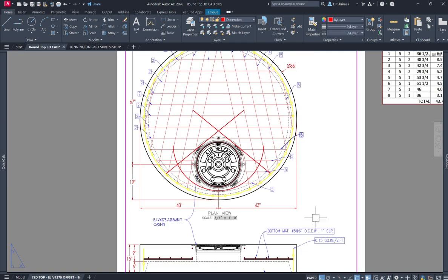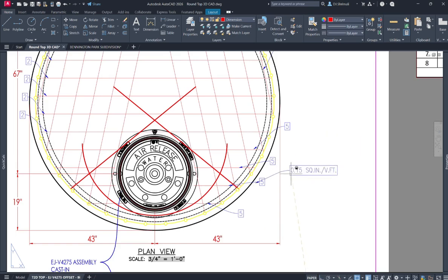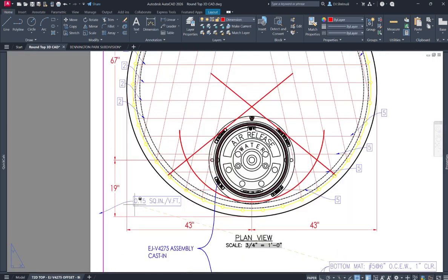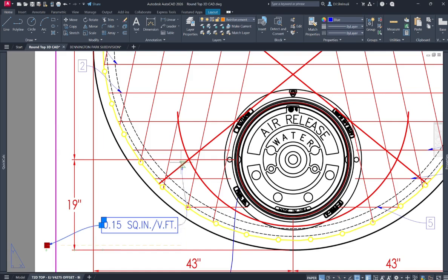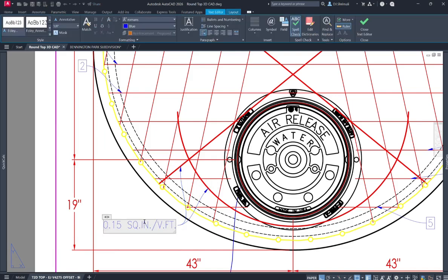And right now I'm just using the copy command for all of it. Since these are special rebars that are not like number 5 at 16 or something, these are diagonal rebars, so I'm just gonna place a tag or description that they have to use number 5 diagonal rebars and a bend bar, since one of them is a bend, so diagonal and bend bars.